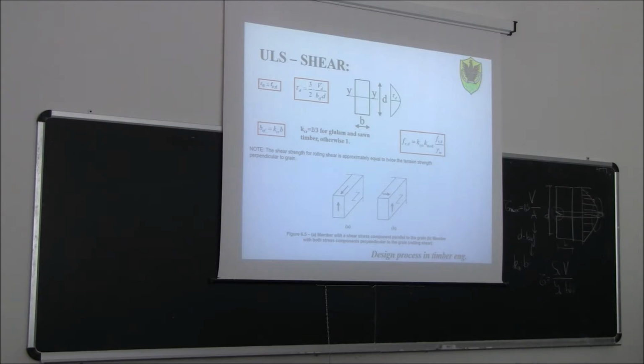So if it's not perpendicular, it would be parallel. Any plane parallel to the grain is potentially a weak plane because it's going to shear off only the less resistive matrix. So which planes here are parallel to the grain, so potentially critical?